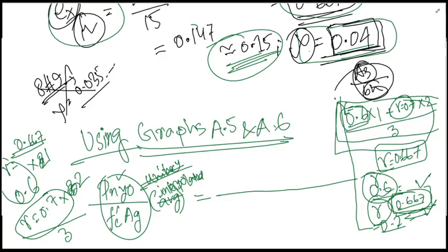As you can see here, 0.1 and 0.2 are there, and there are different marks. If you extend this particular line, the 0.15 line, and connect it with the zero point there, it will automatically intersect. As you can see, all the lines are parallel lines. These lines represent rho g, that is the reinforcement ratio, and if we recall, the reinforcement ratio we are using here is 0.04.